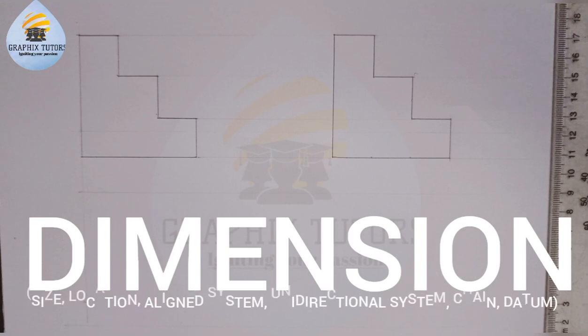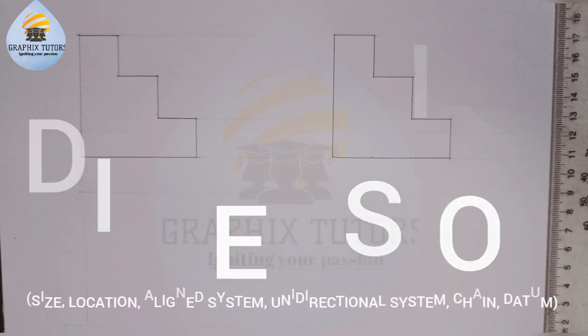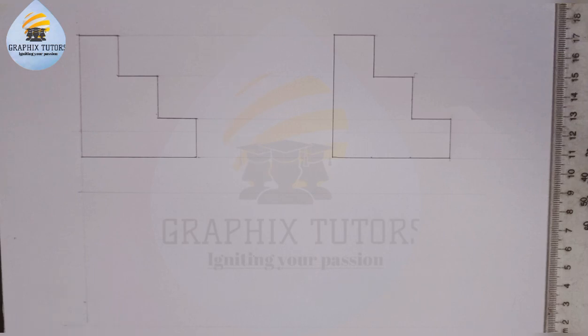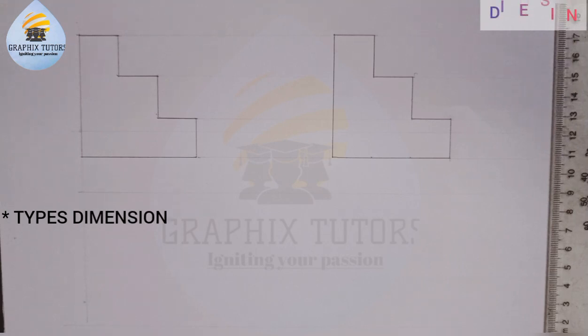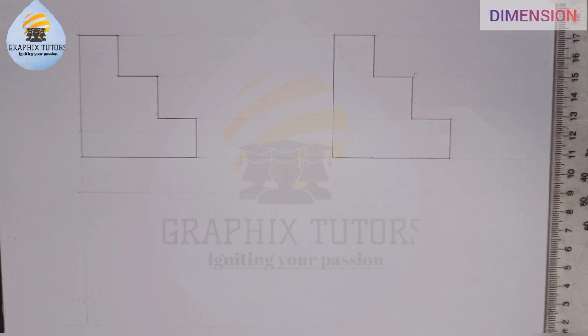In this video, we'll be talking about dimensioning. Dimension is an important attribute in drawing, right? And we have two types of dimension. We have the size dimension and the location dimension. Now let's look at the size dimension. One thing you need to understand is your size dimension can be of two types. We have the chain dimension and the datum dimension.